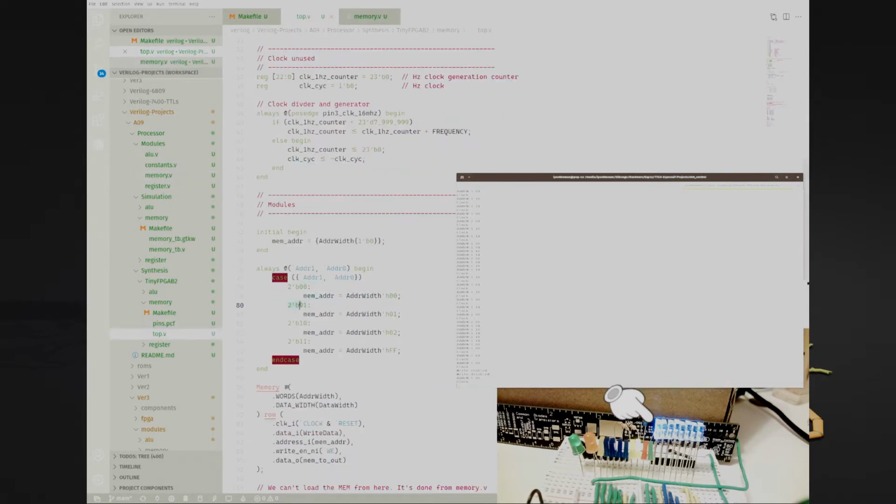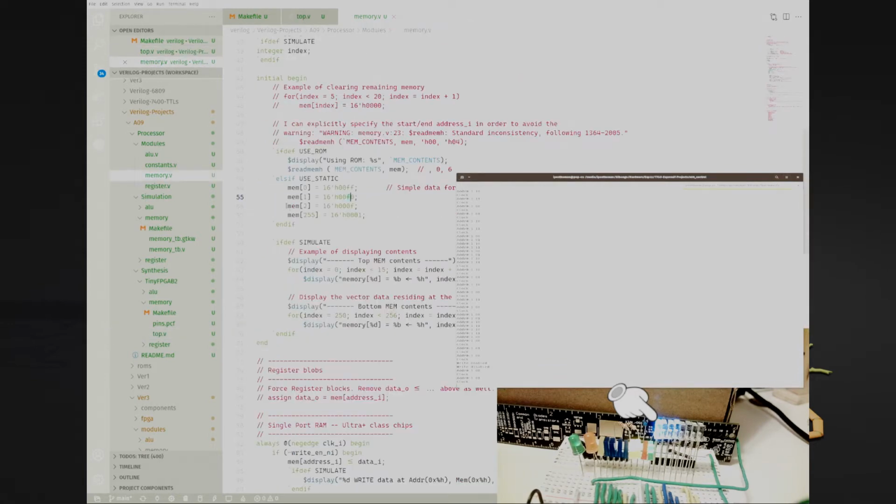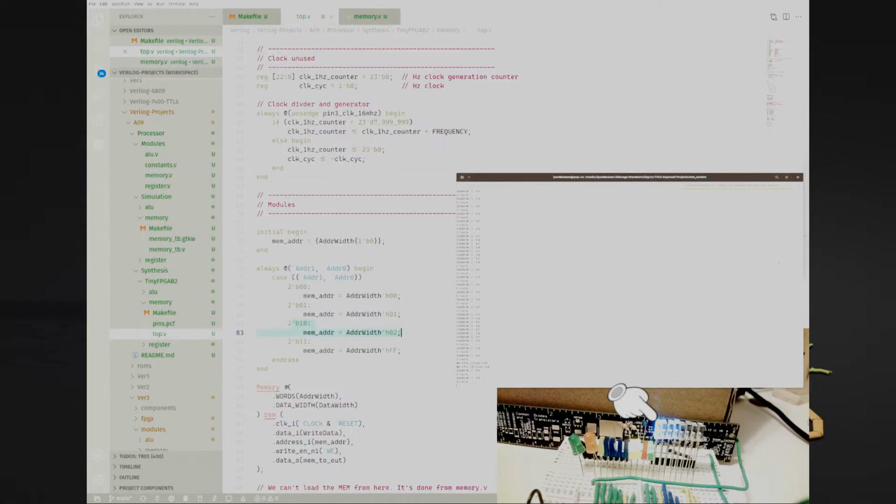So I'll switch the addresses to 01. So I'll hit the letter B and then clock it with the letter X. And there you go. We have FF or F0. And we can check that for the next address, which we happen to know is 0F. So let's do that. We'll hit the letter C for the third address, hit X, and sure enough, the lower 4 bits are high. And of course the last address, which is FF, we'll do that one.